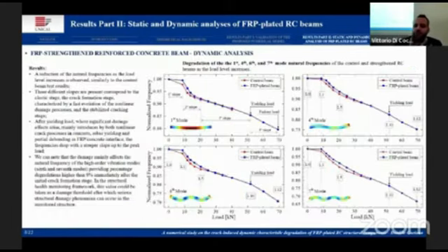Solving the linearized eigenvalue problem for the FRP-plated beam, we can see in this slide the reduction of the normalized frequencies for 4 selected mode shapes. Each path has 3 different slopes. The first is related to the elastic stage, the second corresponds to the crack formation stage, characterized by a fast evolution of the damage processes, and the last corresponds to the stabilized crack phase. After the yielding load, the frequencies drop with a steeper slope up to the peak load.